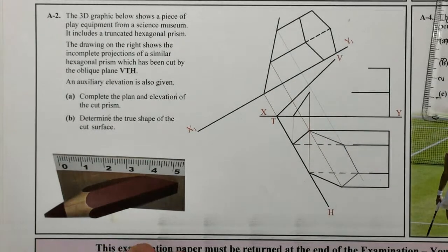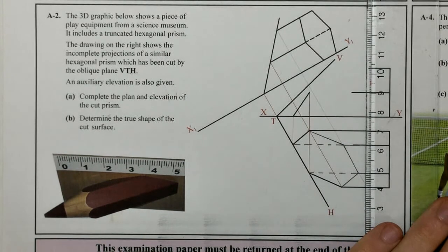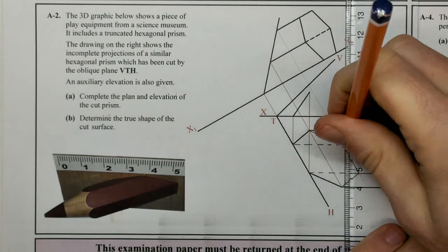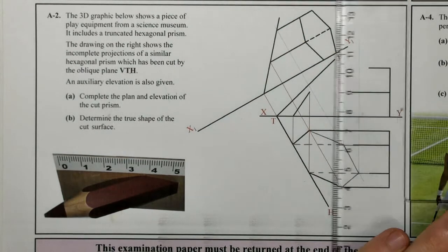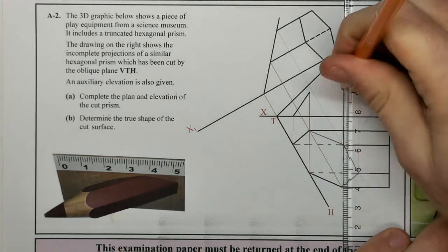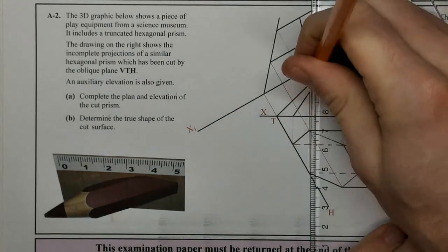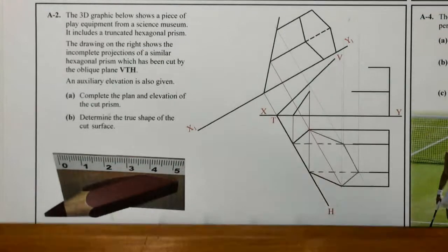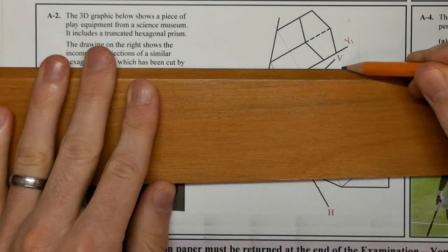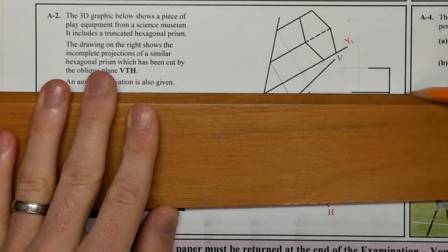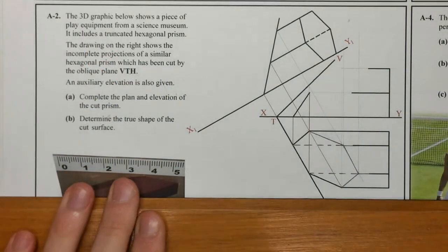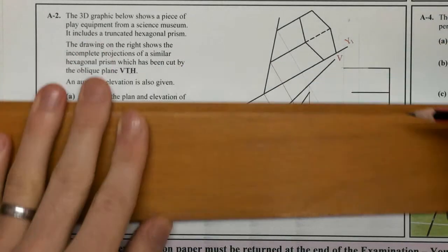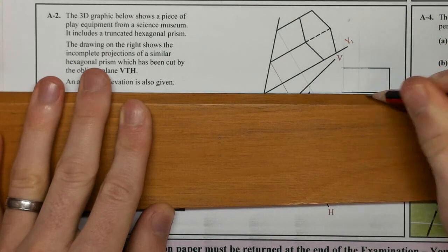Okay, and now we can just project those edges up into the elevation. So vertically straight up. There on the top edge, so that's 2 points up there. Here, and points in the middle. So we projected up already, and I have my base points. So here's my top surface.